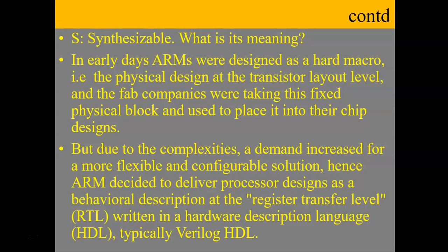When ARM started giving licenses, in the early days, they used to give only the hard macros. That is the physical design at the transistor layout level. And the fab companies, whether Intel or Samsung or any others, would take this physical design, this physical block, and place it into their chip designs directly. But this physical design was not configurable. When they wanted to configure or modify or make some changes, it was a very risky or cumbersome process. Therefore, these people started asking for a synthesizable